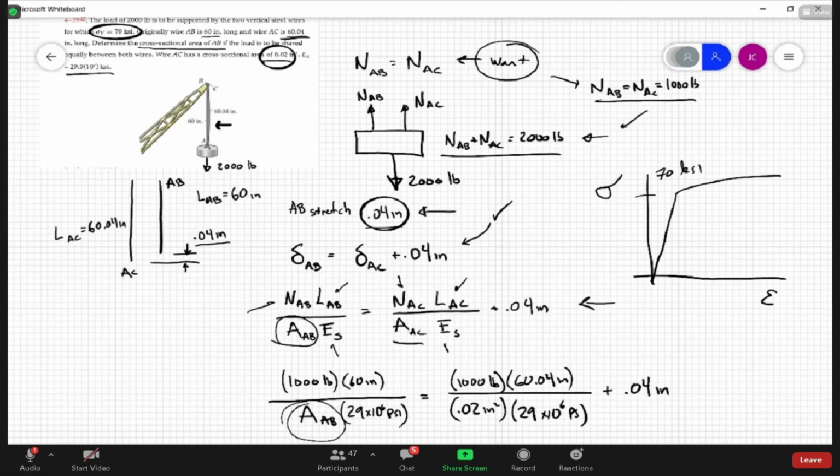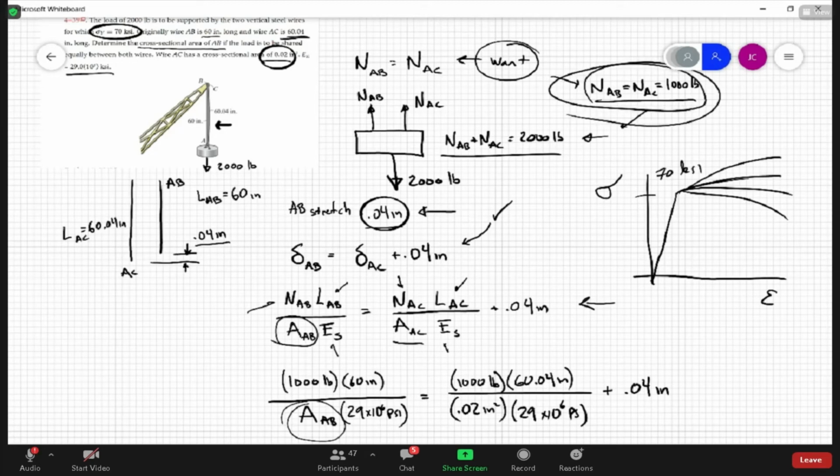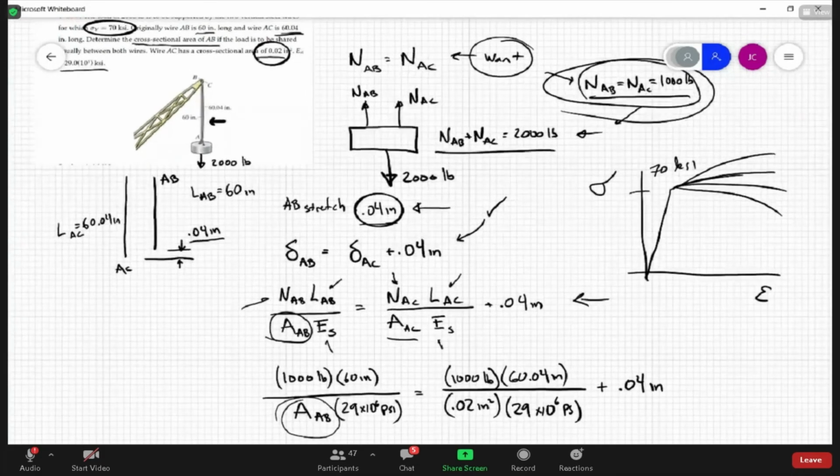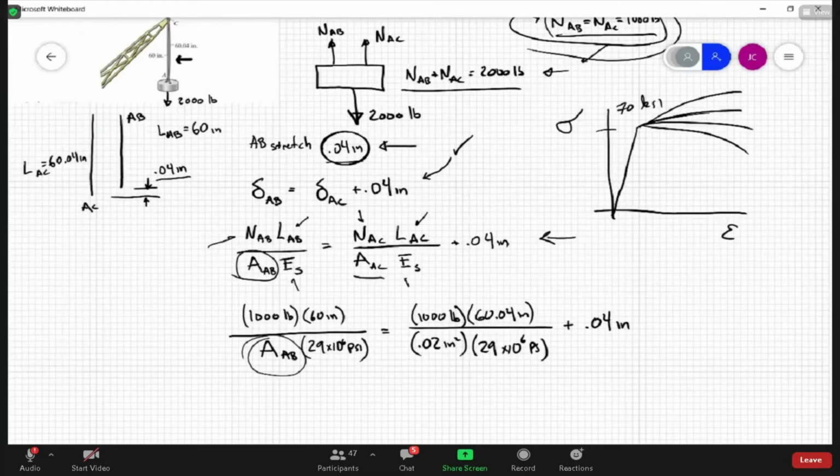Like if I'm up here, I don't know whether the curve looks like that or that or that. Does that matter? Well, no, I guess it doesn't matter because they both have the same material response, and they're telling you that you have the exact same load in each one. Oh, but the area is different. Yes, so your stresses could be different.